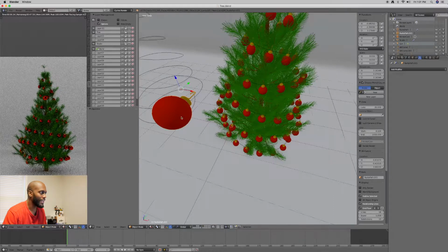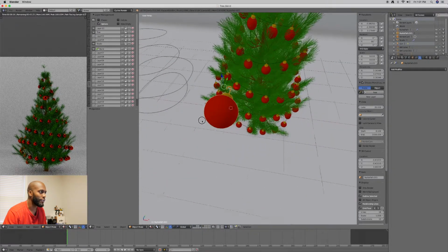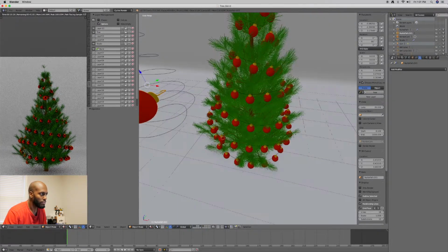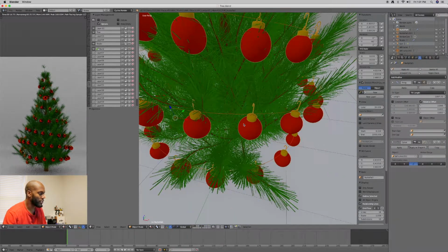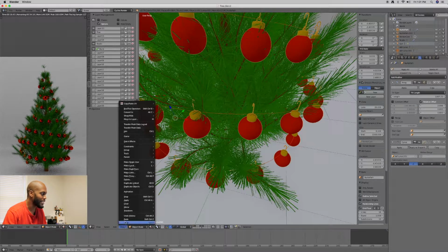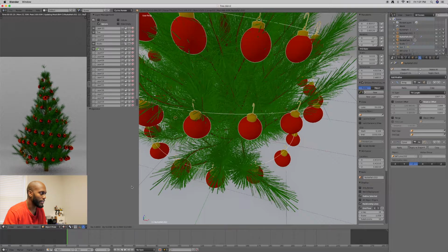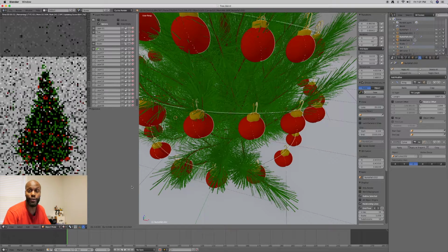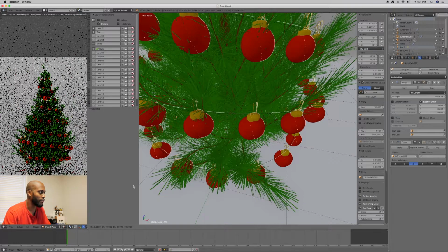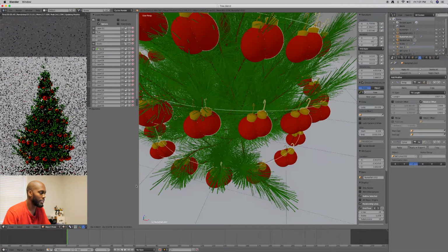Since we know this is duplicate link, we're just gonna use this as a guide layer for creating new shapes. But for now with these, we're gonna select the curve, select the object, and make sure you push Control D, or Object, Duplicate Object. If you move the cursor before you click, it'll move.